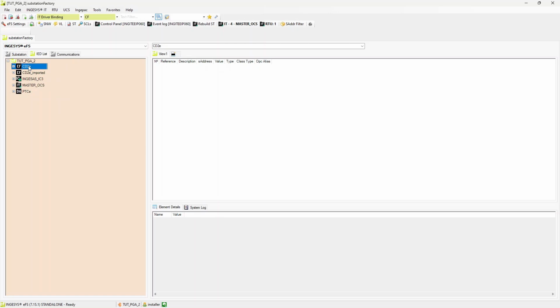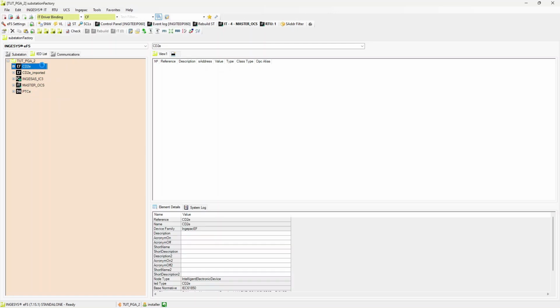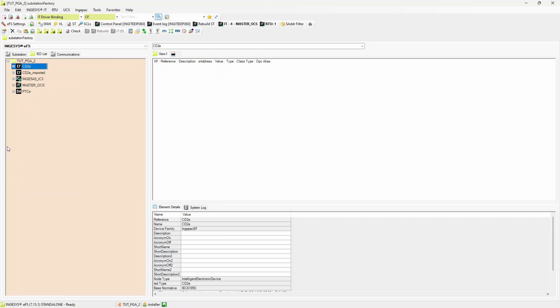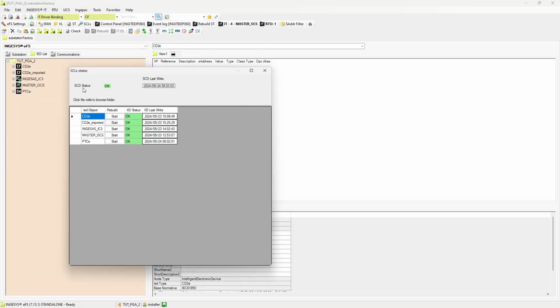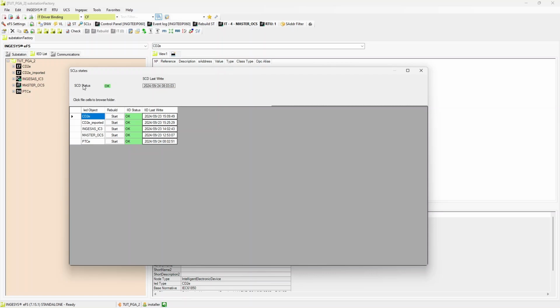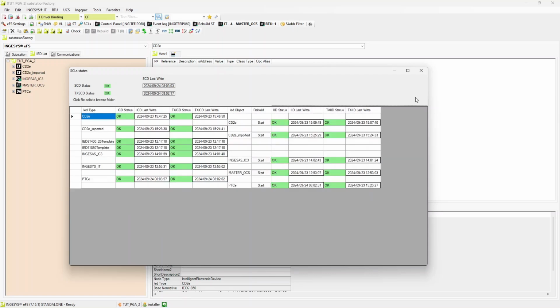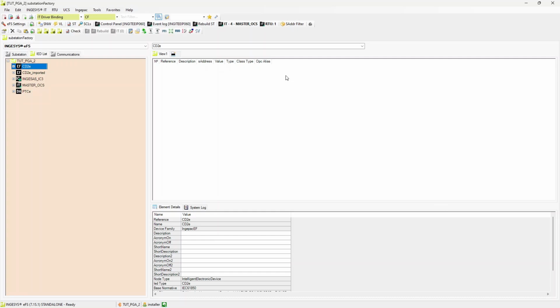If we right-click on the IEDs in the substation, we will also be able to send the selected CID to an IED via the FTP protocol. Among the toolbar icons, the SCL status icon shall be found, which will let us check the current generation status of the configuration documents in the installation. CIDs can also be sent to an IED with this toolbar symbol.